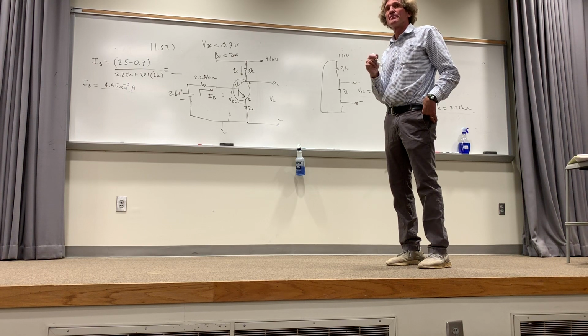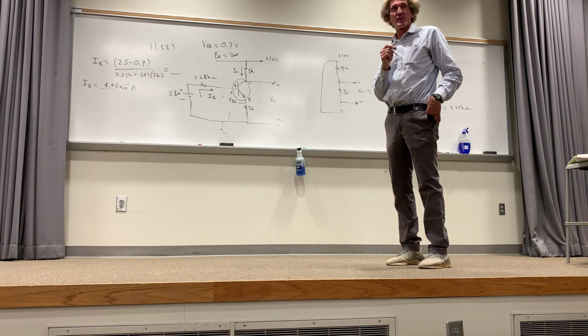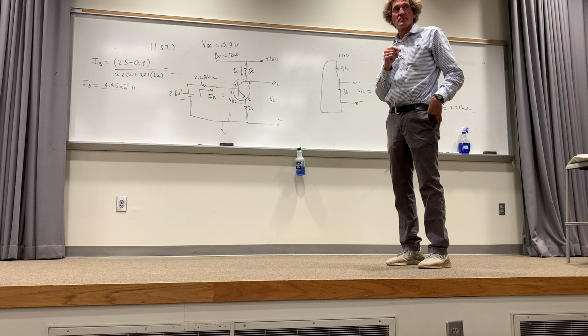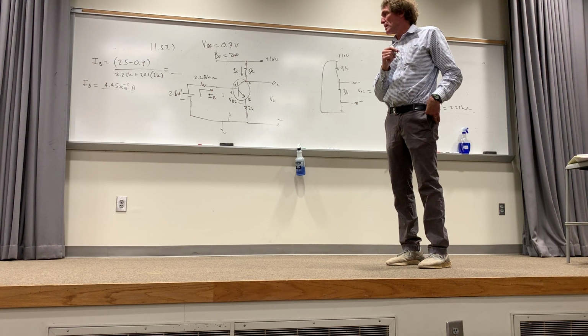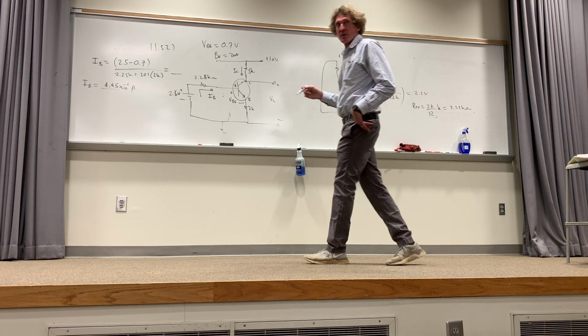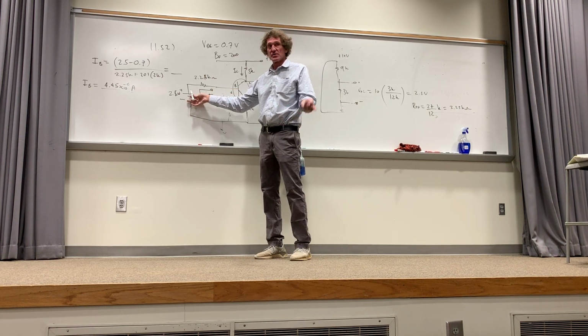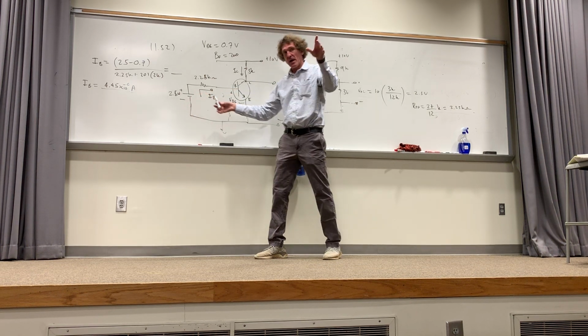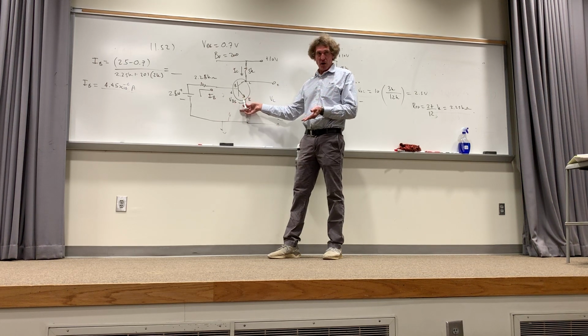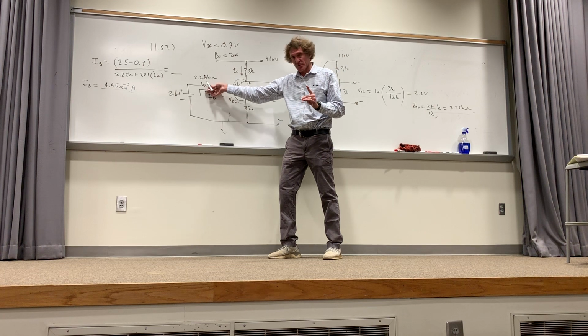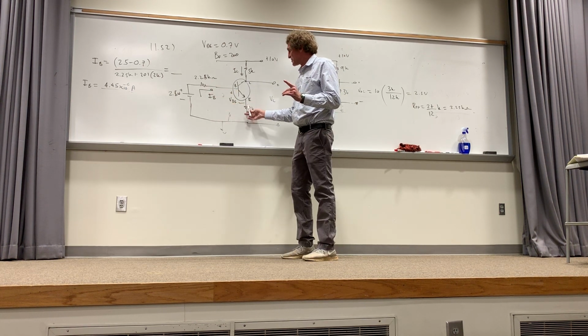What were you gonna say? Did you have your hand raised? Can you go over how you got the bottom of the IB equation? Yeah, I'll do it. If you look at this, first, this 2.5 volts is gonna drive current, right? The thing you have to do is always take the VBE off, right? So that's that. But what limits it? Well, that resistance does, right? But with this resistance, what happens?